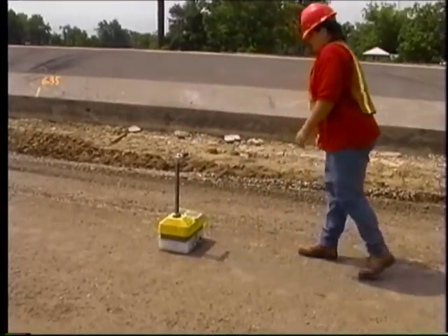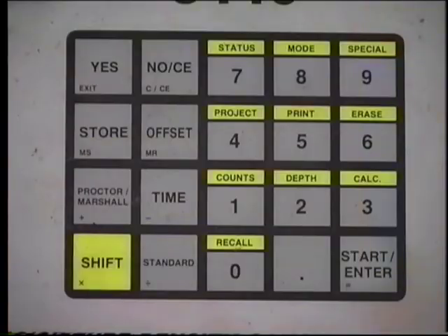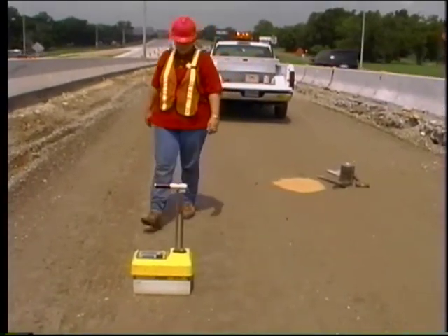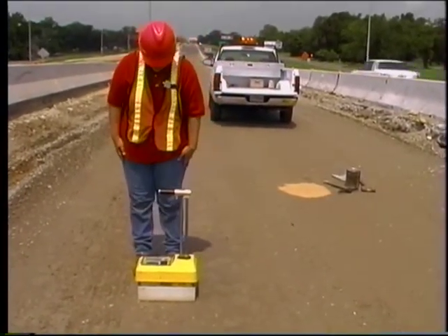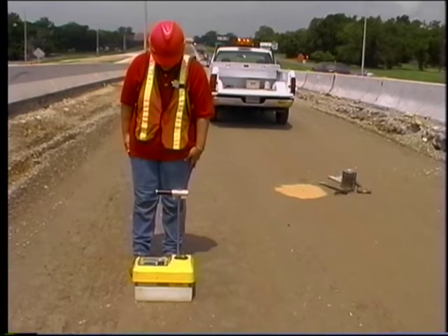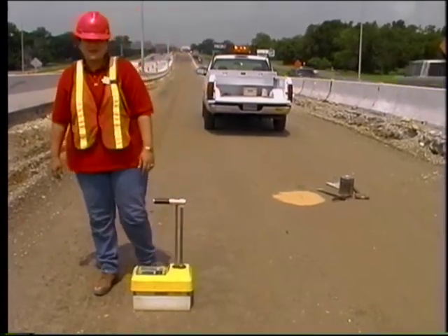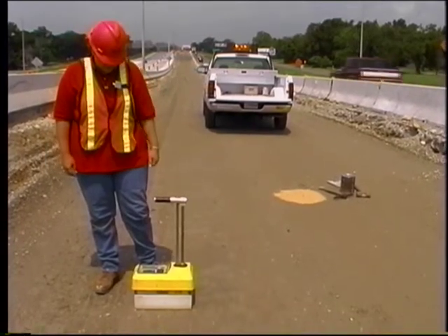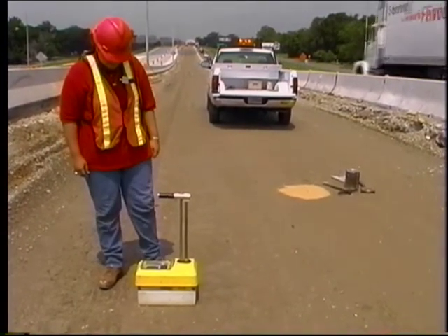If all other conditions are normal, don't accept the standard count just taken. Press No and take another standard count, regardless of whether or not the cause of the failing percentage was identified. If, after having taken 3 additional standard counts, an F still appears in the display, contact your supervisor, who will contact the district laboratory engineer before sending the device to the materials and testing section for evaluation.